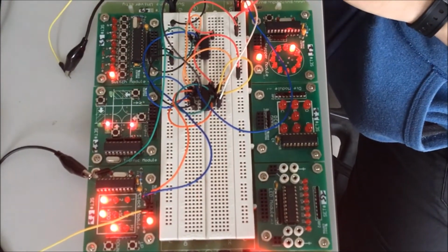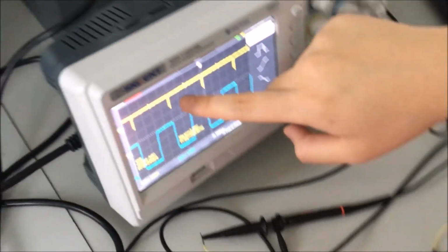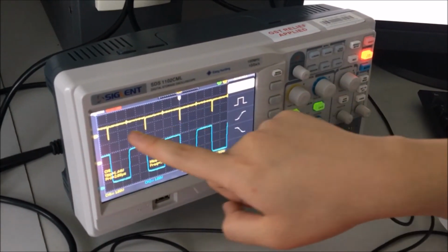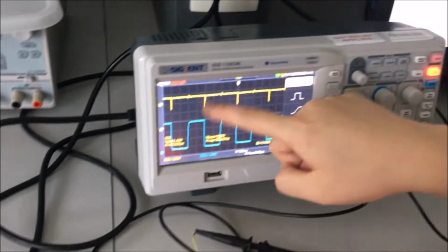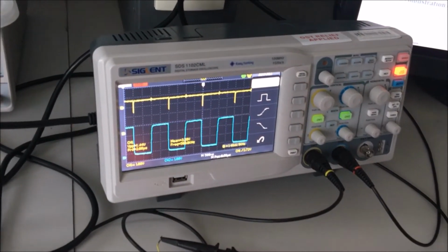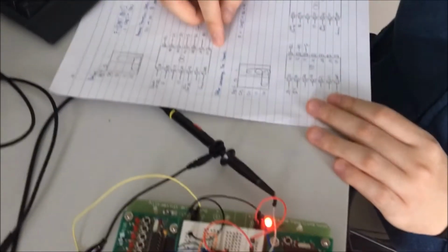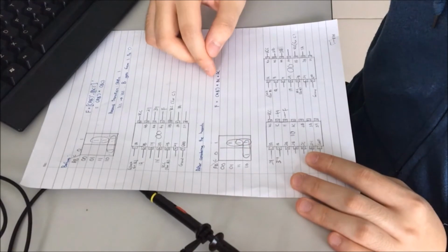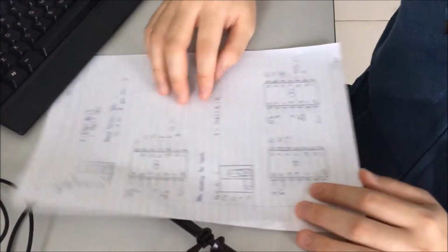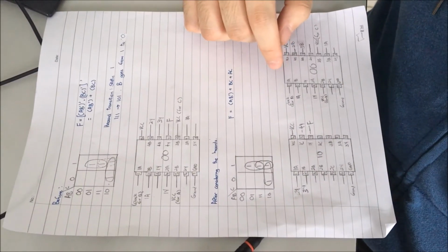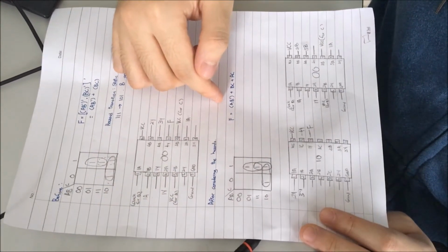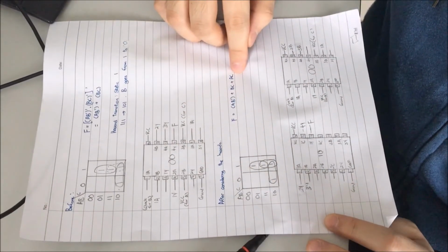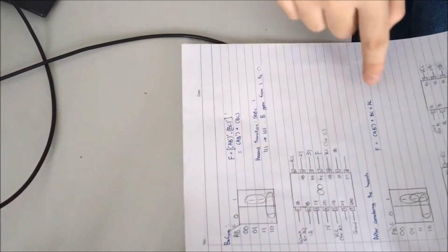As you can see, we have already obtained the static 1 hazard, where it's normally 1, but it occasionally dips to 0. After considering the hazard, you can see that we can add a prime implicant here to cover up the hazard. Now, to eliminate the hazard, we added this new prime implicant, which is AC.